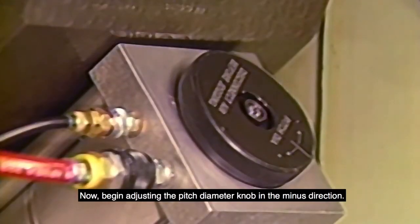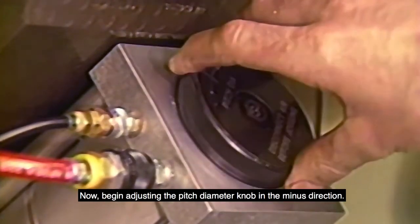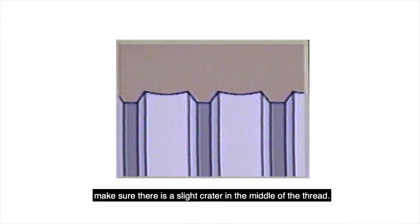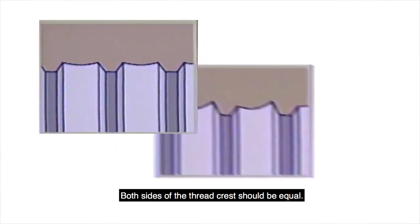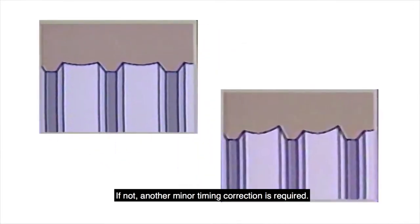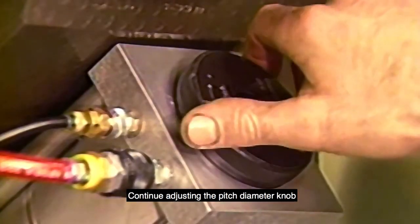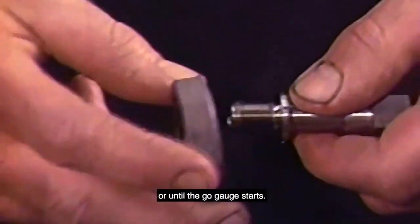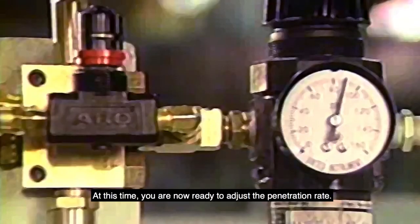Now begin adjusting the pitch diameter knob in the minus direction. Using a glass or loop, make sure there is a slight crater in the middle of the thread. Both sides of the thread crest should be equal. If not, another minor timing correction is required. Continue adjusting the pitch diameter knob until you reach the high side of the pitch tolerance, or until the go gauge starts. At this time, you are now ready to adjust the penetration rate.